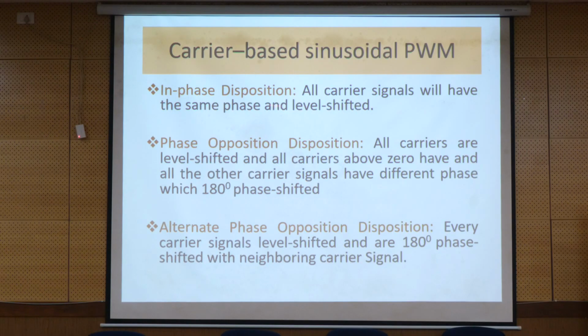This is done by simulation and experimentation, based on one reference parameter, the THD value. Whichever switching strategy gives the minimum THD will be taken into consideration.